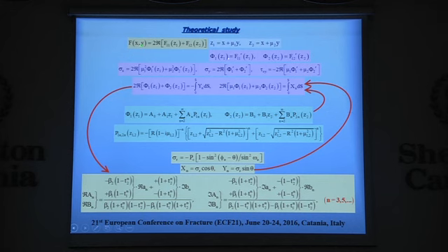So we introduce these complex potentials in the previous expression we have seen for stresses. We obtain stresses, and here are the boundary conditions for stresses in terms of these complex potentials. Once we have obtained these complex potentials, then we have the full stress field on the disk's cross-section. And these are the complex potentials; I have told you before, we take from Lekhnitskii the general form. So we introduce them into these expressions, expanding the right-hand sides in Fourier series form, and combining coefficients to finally obtain the coefficients of this complex potential, so we have the full stress field of the disk.